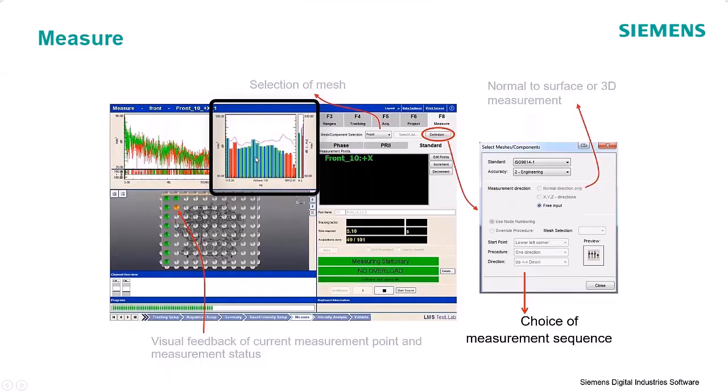If it is showing blue or green, that means the measured intensity is good data. If you see red, which can happen in some octave bands, that means there is a negative intensity value. Sometimes your probe is not facing perpendicular to the surface, or the orientation of the mics in the probe is such that you have declared one mic to be at the front and one at the back, but you're not pointing the probe that way. Then all the intensities you measure will be negative. So having this visual indicator helps you quickly determine whether you're getting good quality data or not.